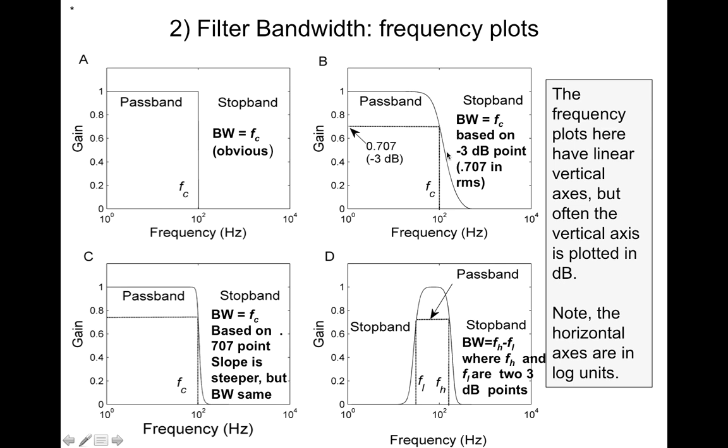Also notice that you're going to pick up some frequencies in your signal that's being passed that are not frequencies necessarily that you would want, because you don't have this perfect vertical slope. So different types of filters with different design impact this attenuation slope. And just depending on how stringent your requirements are, that determines how you would design your passband and your attenuation slope of your filter.